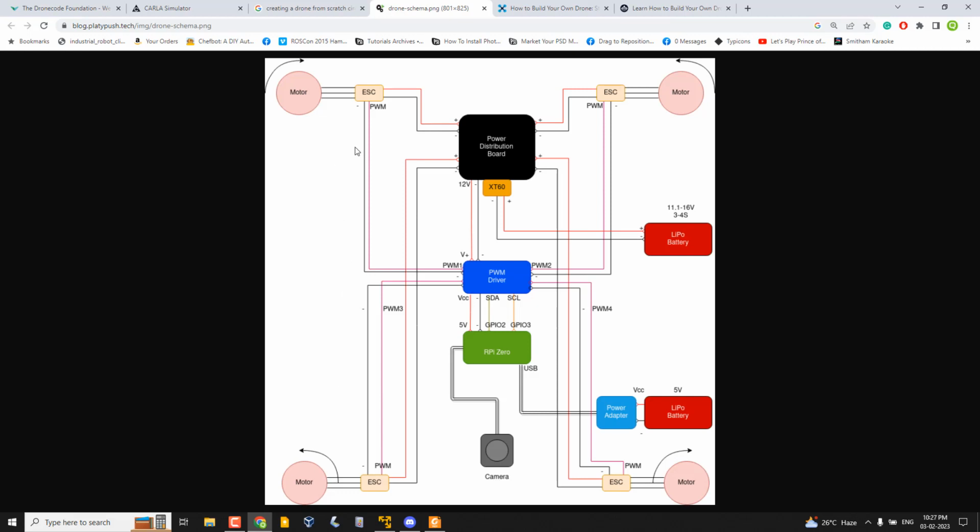The circuitry is different, but the objective is the same: both circuits control the speed. Here you can see the ESC has three pins, but the H-bridge has two pins, because brushed motors only have two pins, right?